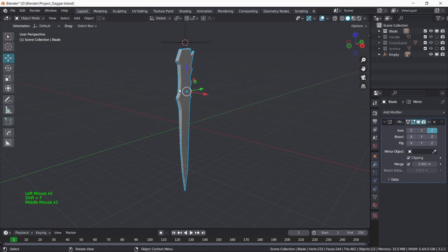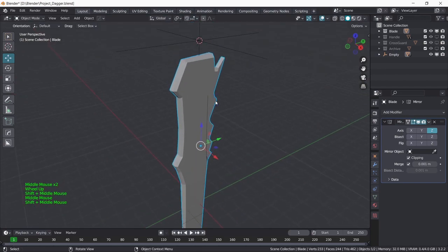So what we're gonna need to do now, there are two things you can do. Either if you want to create a really nice high detailed model, high poly model, you can keep on working on this and making it better, using subsurfaces and different modifiers, and that will turn out to look really good. If you want to make some kind of asset for a game or something low poly, you would probably not want to make something with so many polys, and so we would not be using subsurf and other modifiers.